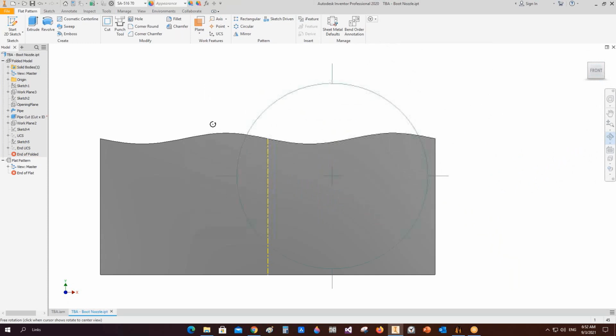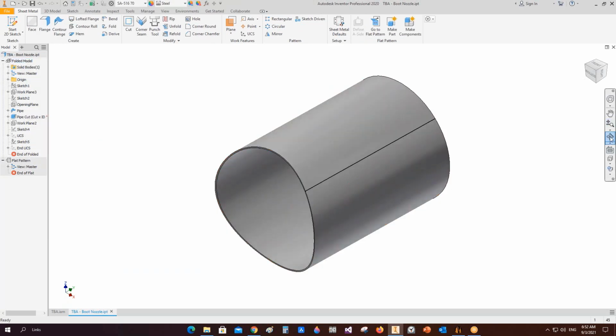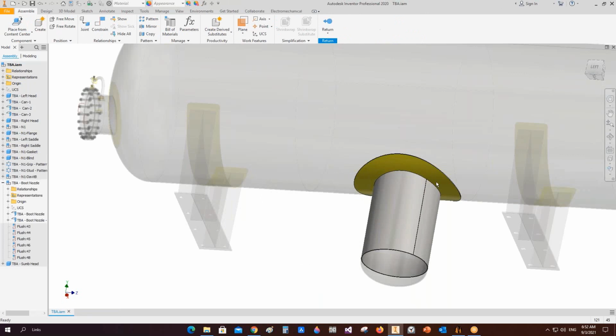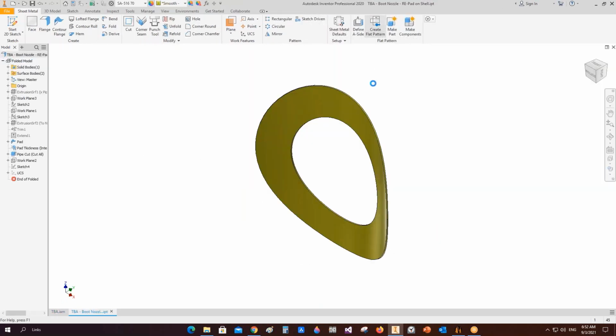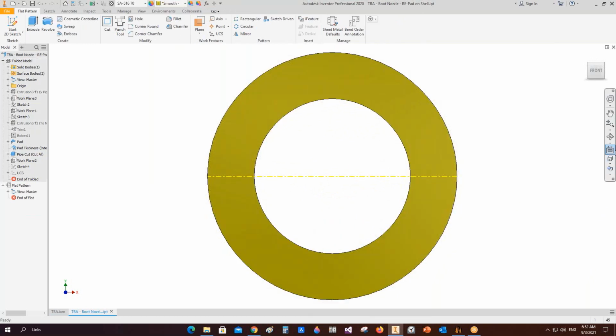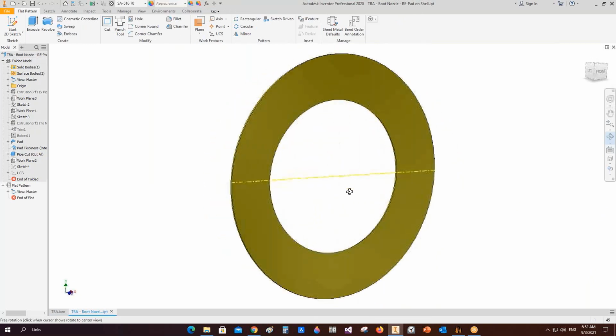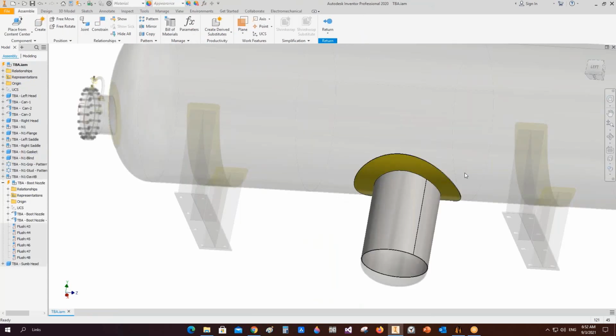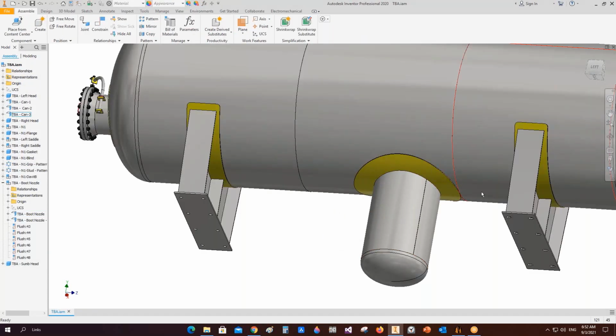So that's the contour of cutting to get this pipe of plate. Okay, the same for the weir plate. If you would like to get the sheet metal flat pattern for this one, you can get it directly. And there is an automation tool here that can get all sheet plates for your project at the same time.